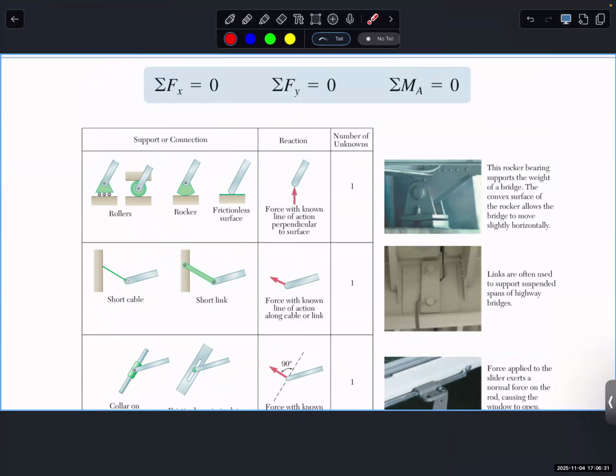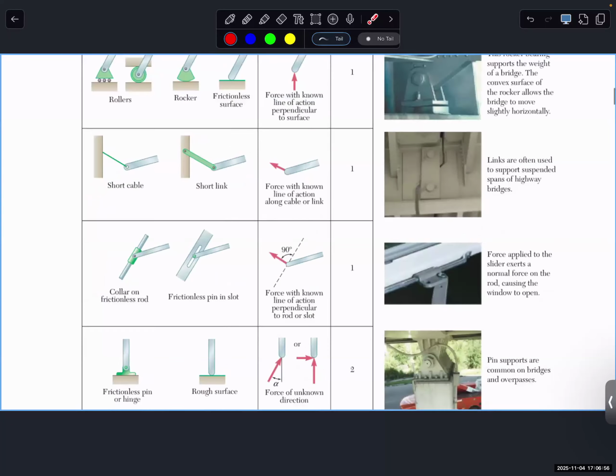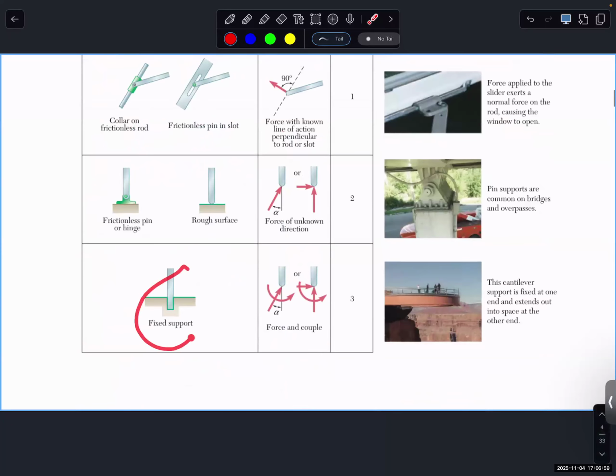And you consider, if you do the free body diagram of this tooth itself, the force you apply, let's say you have an attachment, you have a wire or anything, the force applied on the tooth, and the PDL connected with the bottom part is considered as a reaction force. So in different boundary conditions, it provides different reaction forces. So the PDL basically fixes the whole bottom part. And in FEA, we can consider it similar to a clamp situation.